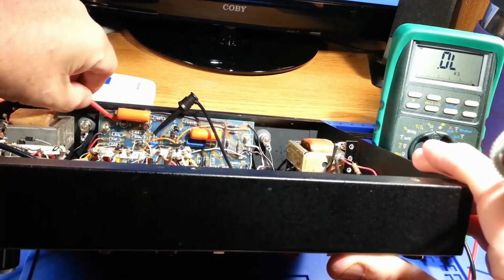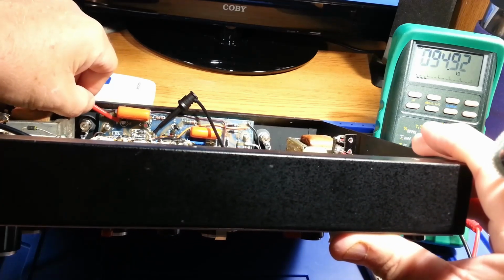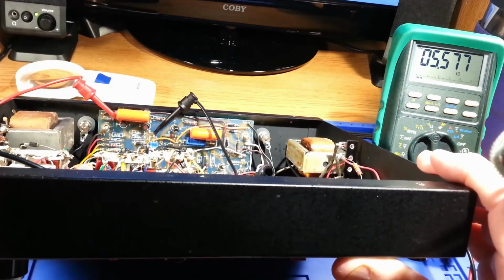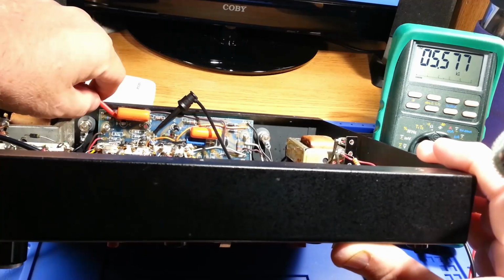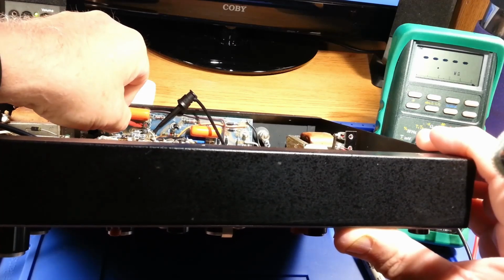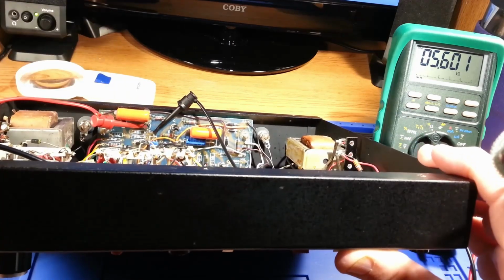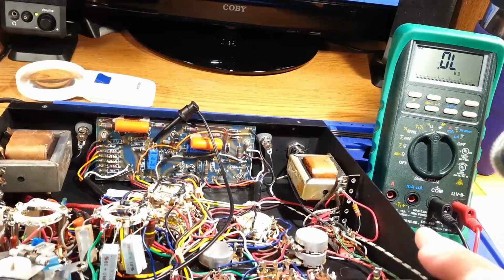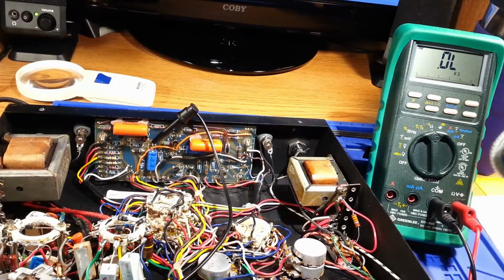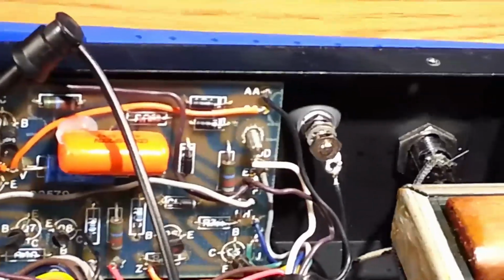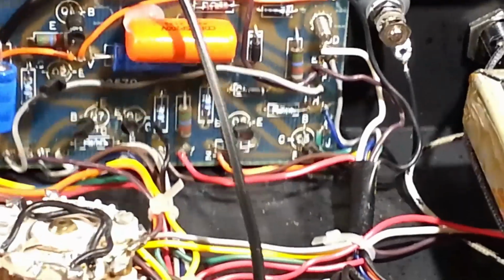Always working on stuff is always fun. You find a way somehow. There's the collector connection. If you look at my meter, I got 5.6 kilo ohms. And Q3, same deal, 5.6 kilo ohms. And there's no way that that's going to go through to 5 and 6, because 5 and 6 are marked all the way down on the bottom part of the board here.